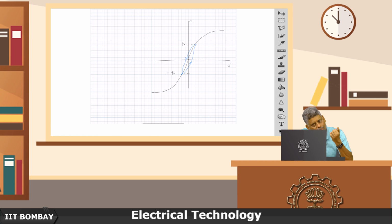When you talk of magnets, their remanence is extremely high. They require much better magnets which cannot be quickly demagnetized. So, they may require a lot of H application to demagnetize them, otherwise they may lose magnetism very quickly. So, magnet design is a different topic, but the same concepts are also required when you talk of the design of magnets.